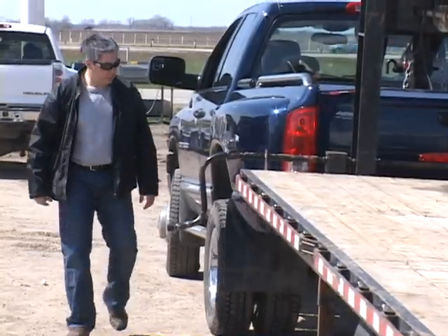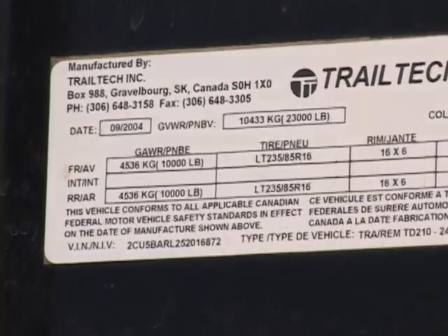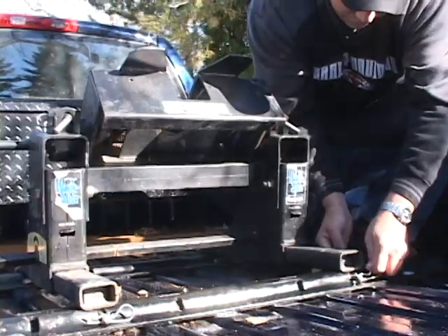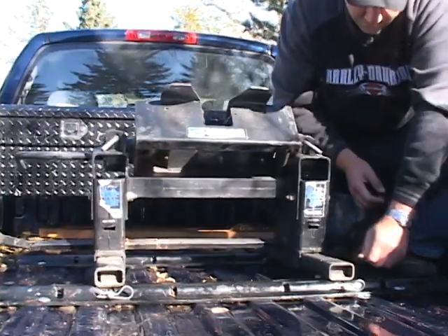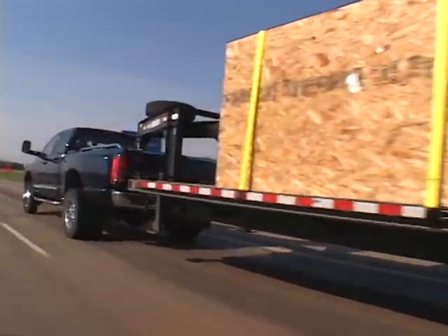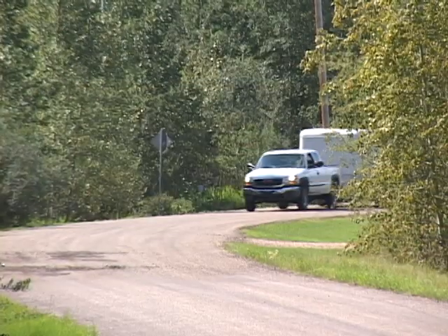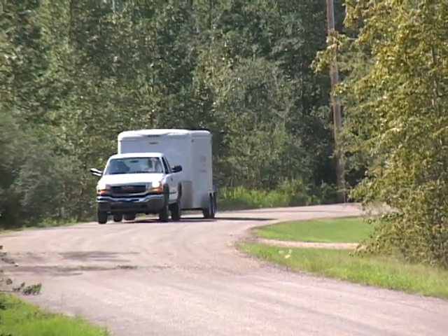Prior to loading cargo onto or into any trailer, ensure the trailer is rated appropriately for the total cargo weight. Also, check the load ratings of all hitch components. Whether using a flat deck or an enclosed trailer, weight distribution and the need to secure the cargo to exclude the chance of a load shift is extremely important.